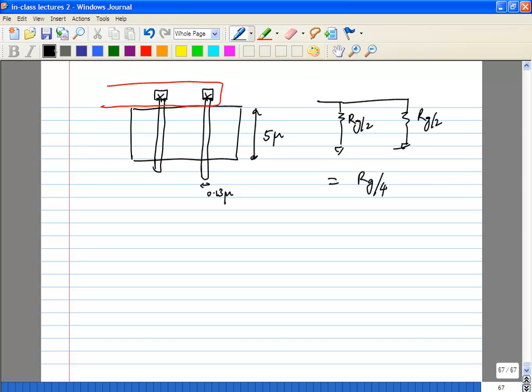Remember we have not considered, for example, capacitive parasitics. Those kind of things will start getting suboptimal after some point of time. So normally I wouldn't go below a micron of width. In your case it probably won't matter. It will matter more when you do the layout and run an extraction for your parasitics.